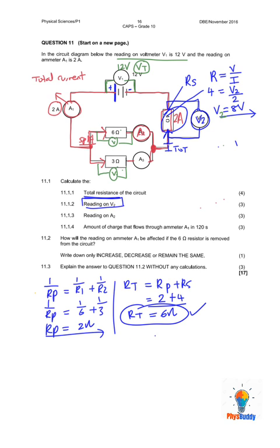And we also know that the total voltage is made up of the voltage that goes to series plus the voltage that goes to parallel. So from the 12 volts, we've already found out that 8 volts go to the series, and that leaves us with a parallel voltage of 4 volts.